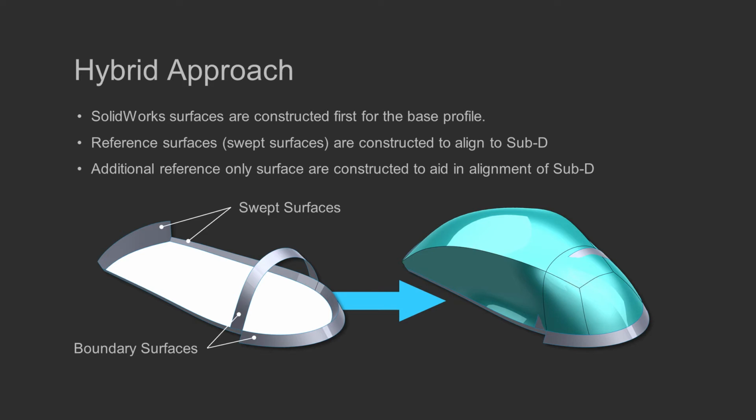So I just mentioned that hybrid between using SolidWorks features and sub-D features. And what I do in this computer mouse is I don't start with just a sub-D surface. What I do first is lay down some primary surfaces, namely the bottom of the mouse, which is the only flat surface in the product, but it's an important surface because that defines the profile of the mouse as it touches the tabletop. Functionally, it's very important because it defines the space for the PCB or batteries and whatnot.